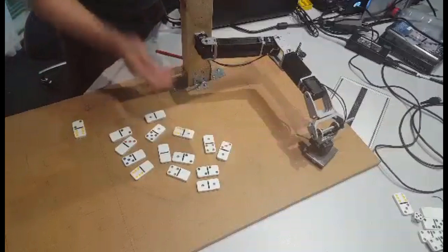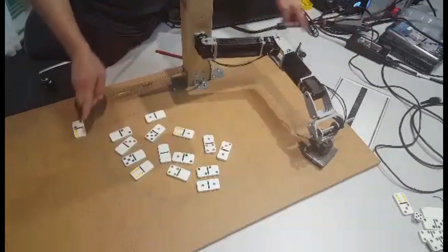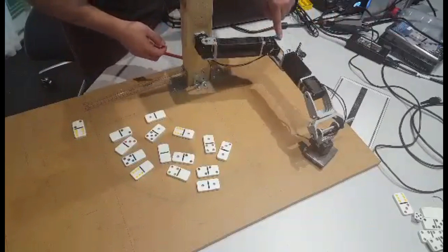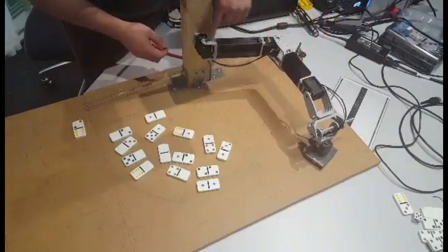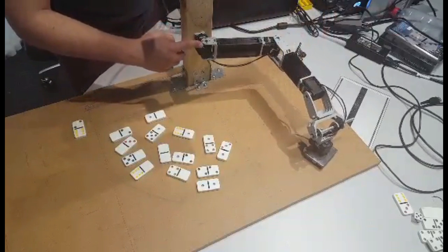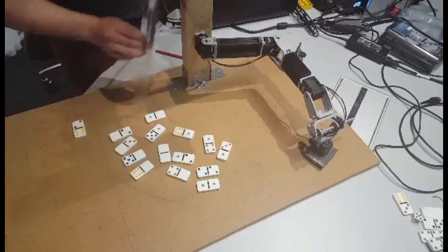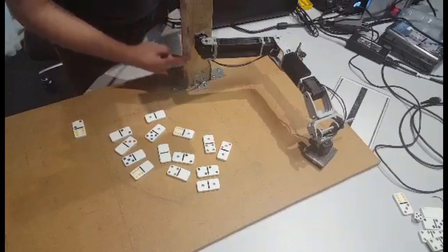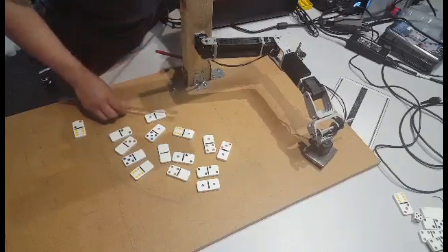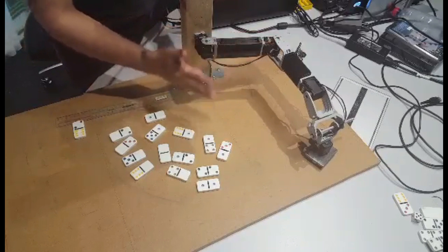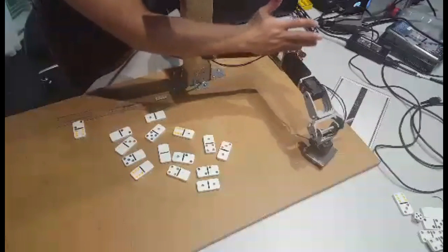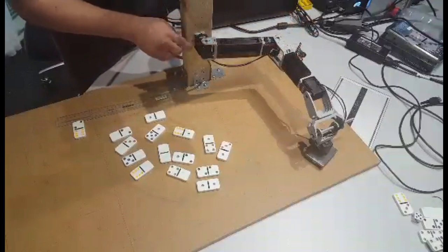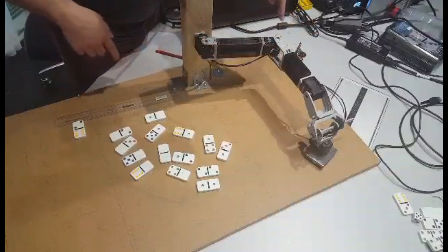The prototype geometry was planned to allow for a great configuration space and avoid large disturbances coming from gravity. Motor 1 is placed at a relative height from the horizontal plane, allowing for a vertical offset. Motors 1 and 2 orientations were chosen to avoid disturbances in the rotations due to gravitational torques sharing the same axis, as is the case with a vertical arm.